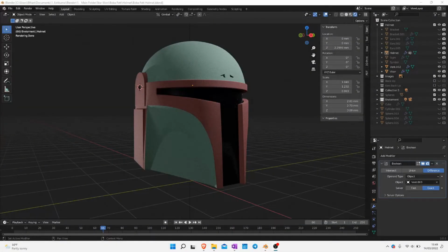Now you may be wondering what you could use the Solidify modifier on, with a bit more of a use case. And it comes in really handy when you're designing helmets, especially helmets in Blender, because you will design with planes and extrusions and cubes and stuff, but at some point you're going to need to add thickness to them, so that they'll be strong enough to print, and they're not just a one-line bit of code.